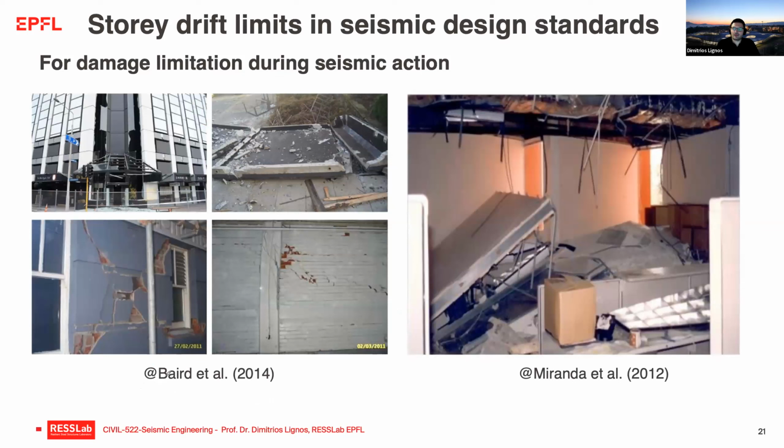One is from 2011, the earthquake in New Zealand, where you see a building that has experienced considerable damage in the facades, also some damage in infill walls. These are not considered to be structural, at least the ones from the infill. The one in the column is considered to be structural, but the one in the facades here is not considered to be structural damage, and can be controlled if we have strict limits for serviceability.